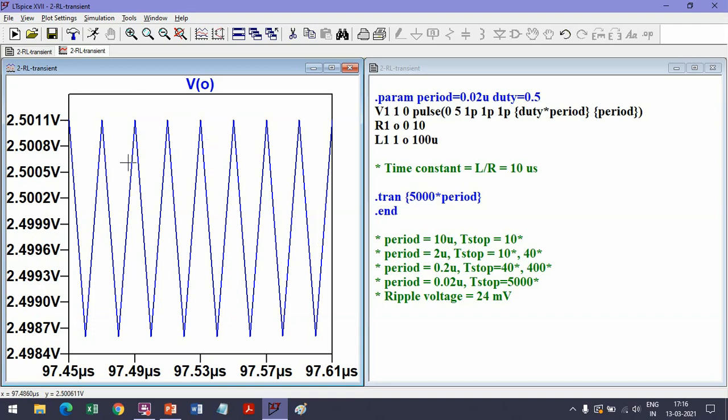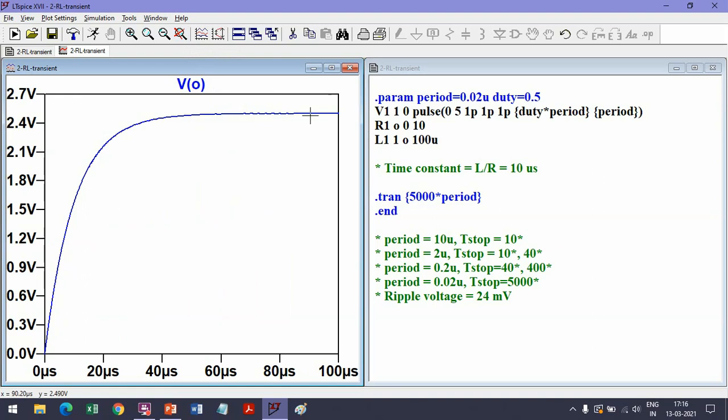So here the ripple is about 2.4 millivolts, and it turns out that for applications of these SoCs, a practically DC voltage with a small ripple is acceptable as a voltage that is input to the digital circuits inside the chip, digital or analog or whatever.